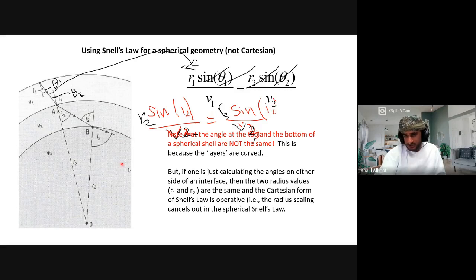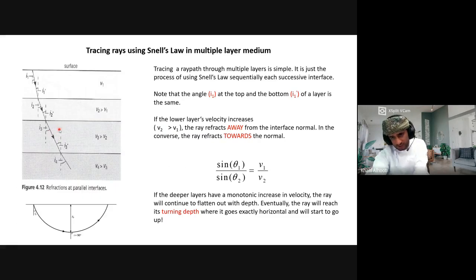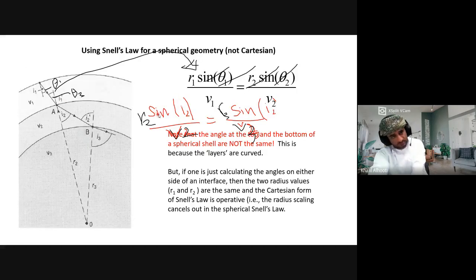In the previous case they are equal because we assume the Earth is flat. But in reality, it's not flat. For small-scale surveys, we ignore that the Earth is not flat. We assume it's flat because the angle difference is meaningless, it's very small. Is that clear to all of you? That's what is explained here. Do you have any ambiguity with what I said?